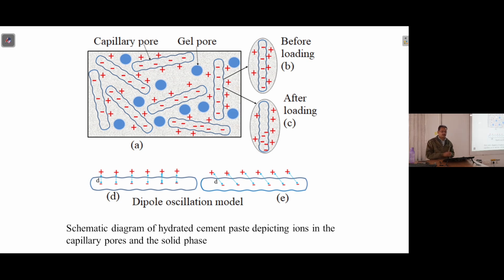Yeah, so for the hypothesis then, what is considered is this, like I mentioned, there is a place in between gel formed zones. These blank spaces which remain there are referred to as capillary pores. These capillary pores have the water which remains there, which is not used by the reaction, and this also has different kinds of ions, calcium, magnesium, and so on.